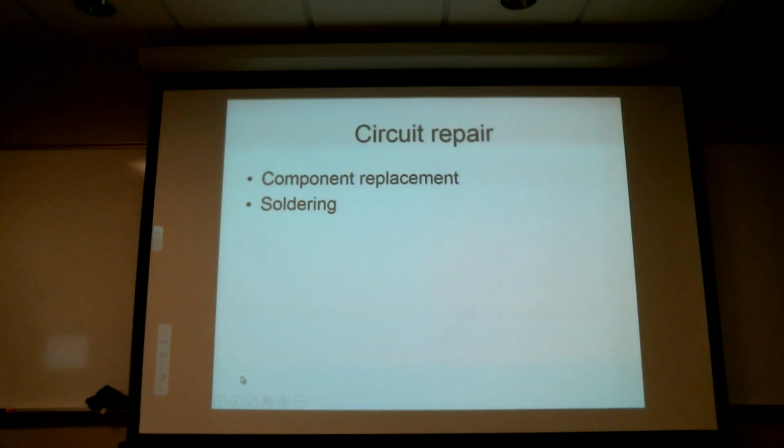And a lot of these, by the way, come from labs. So there's going to be a question about wire lacing. What are some of the requirements around wire lacing? There's definitely going to be a question about the 3-unit regulator. Hopefully you learned something about how that worked. You're also going to maybe be asked some questions about the alternator. So what makes an alternator different? The field spins and the armature doesn't, and it's got a rectifier instead of a commutator, right? And what those things do.